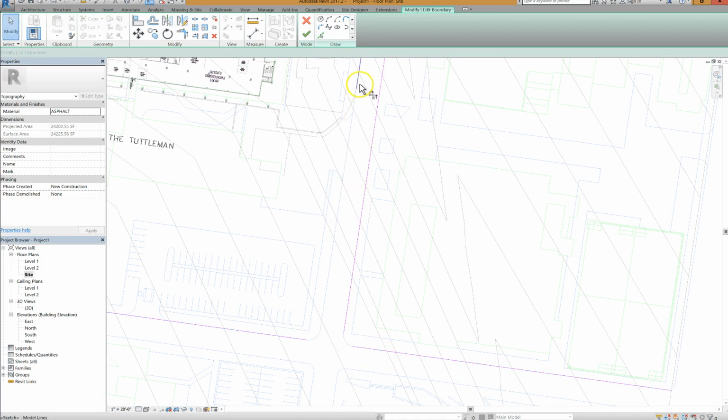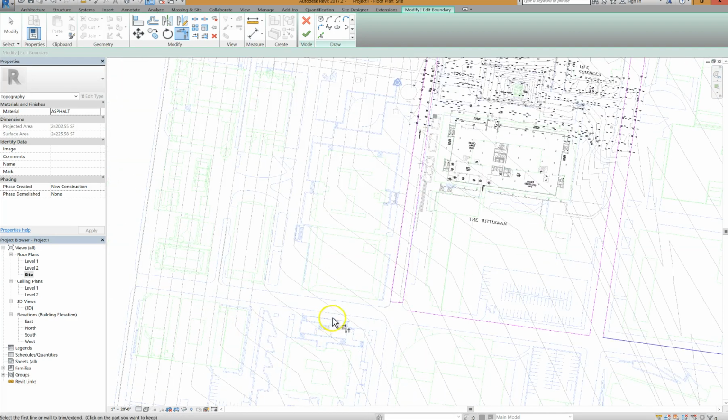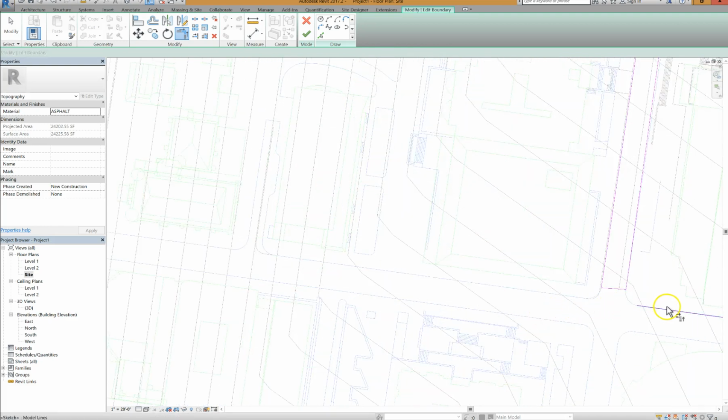And I'm just going to trim these corners off for now, just so we can move on to the next step while making this other street down here. Trim command there. Pick line command there. Trim. Delete that line.